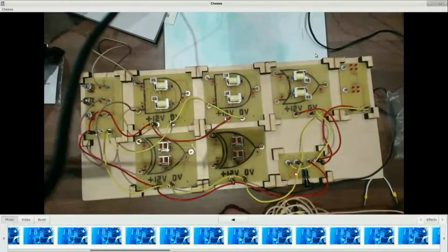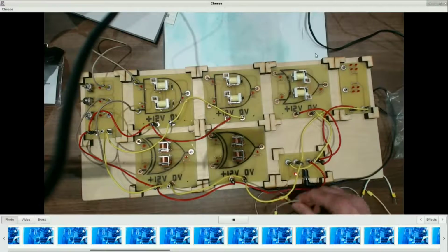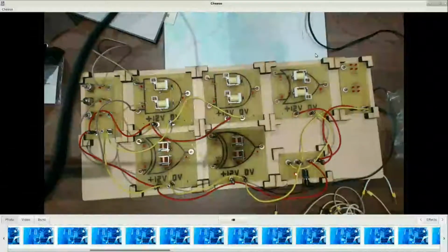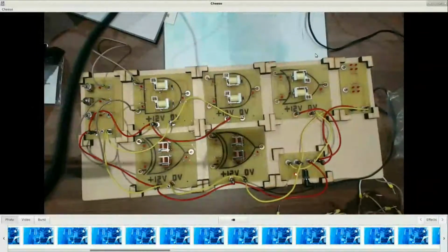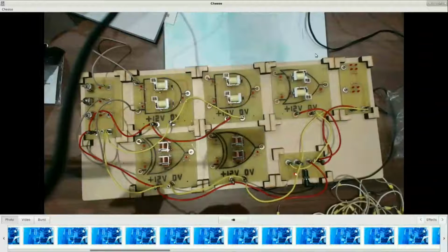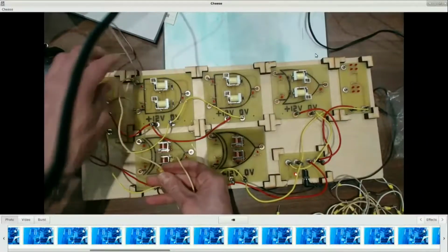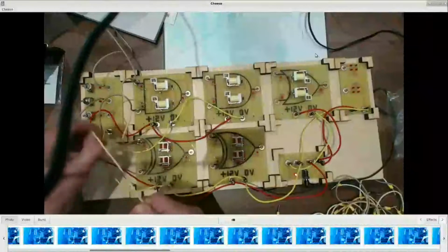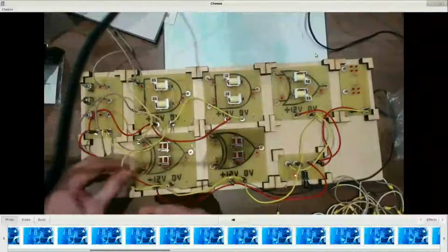What is also connected to those? Do shout out. Another gate is connected to exactly the same signals. It will be the exclusive OR gate. So the same signal going down to my exclusive OR gate down here. So that makes up my first half adder.